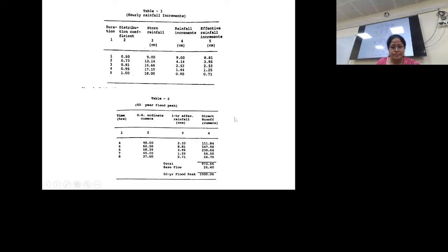So basically, we are getting some catchment area that we can derive either from the toposheet or from DEM, or any source we can get that catchment. If you go to India WRIS site, they have the catchment directly for the Indus basin. So directly that shapefile also can be downloaded. Now that much progress has been made because the catchment has been delineated. But suppose your study area doesn't have any catchment, you have to do it manually. So we will explain either from toposheet or from DEM.